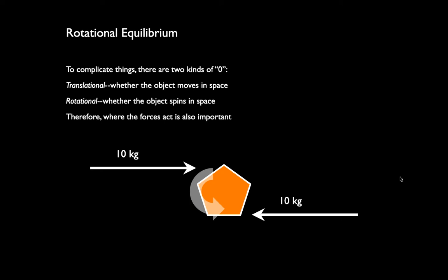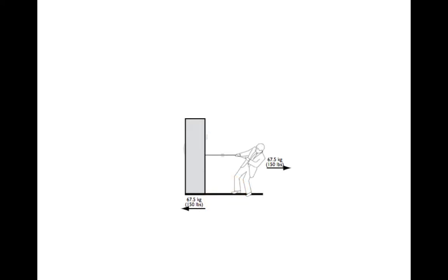If you're trying to unbolt a bolt, if you use a very short wrench, you're not putting a lot of torque onto it. It might be very difficult to loosen. If you use a very long wrench, you'll be putting a lot of torque, right? The same amount of force from your arm is getting deployed in a different place, right? With a longer lever, or a longer what we call moment arm, that's going to make it more effective. Building structures undergo the same phenomenon. And we have to think not only about how much force we're putting onto them, we also have to think about where that force is acting on the building.